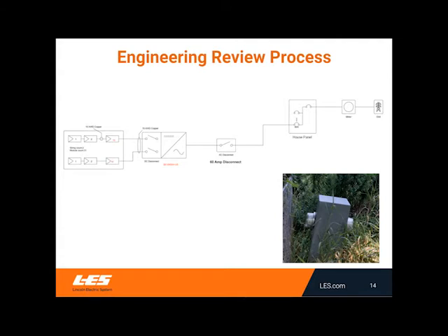And beyond that, there are situations, particularly on acreages or service territory that we have acquired over the years from Norris Public Power District, where we run into meter installations that don't look quite like what we typically would have built in LES's original service territory. This is just an example of one. You can imagine if we see a one-line diagram that shows simply a connection at the meter, and we don't know something like this is out there, when we get there, that usually invokes a whole bunch more requirements or different work on your part.